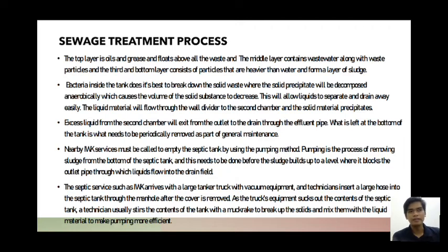Bacteria inside the tank does its best to break down the solid waste, where the solid precipitate will be decomposed anaerobically, which causes the volume of the solid substances to decrease. This will allow liquids to separate and drain away easily. The liquid material will flow through the divided wall to the second chamber and the solid material precipitates. Excess liquid from the second chamber will exit from the outlet to the drain through the effluent pipe.